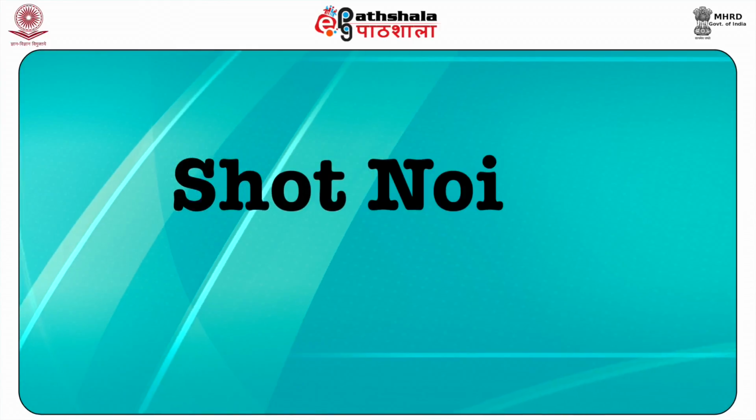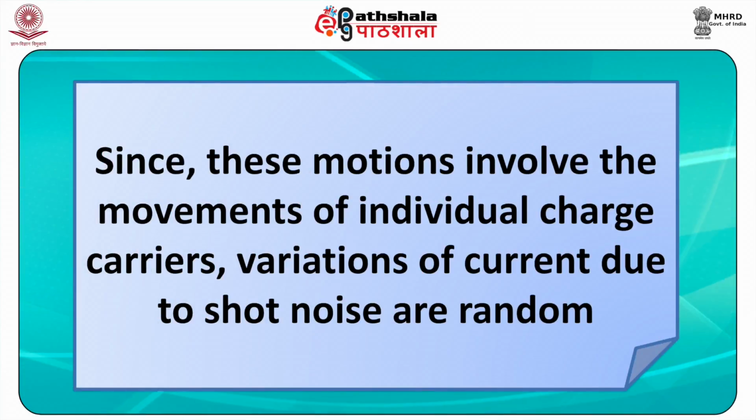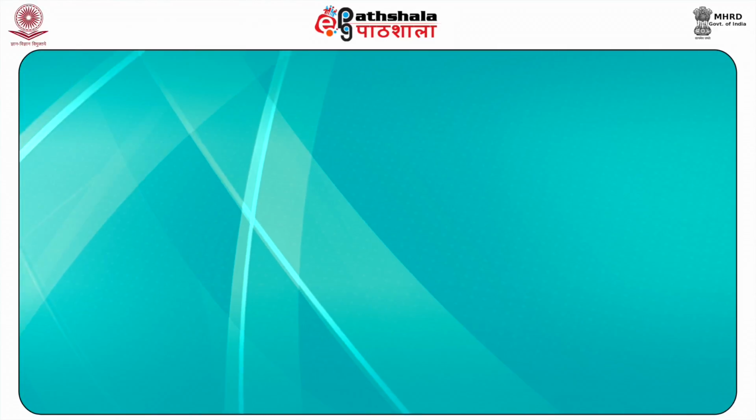Next is shot noise. The magnitude of shot noise is much smaller than that of thermal noise. This noise originates from the movement of charge carriers as they cross the NP junctions or arrive at electrode surfaces. Since these motions involve the movements of individual charge carriers, variations of current due to shot noise are random.